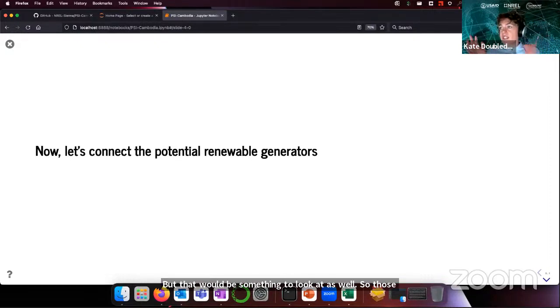So those are some of the summary stats that we can look at once we've run the production cost model. We could also do some other post-processing by, for example, using estimates of emissions to estimate the total emissions from our thermal generators now that we have their set points, and look more into the transmission line flows if we do have congestion issues.